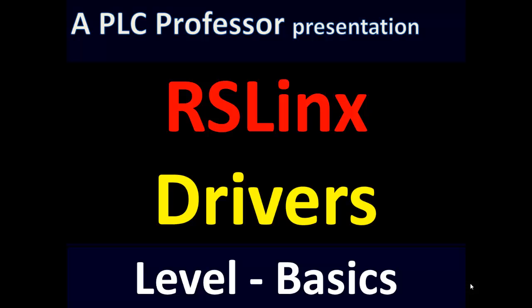The Micrologix 1100 also affords us the opportunity to configure the Ethernet devices driver and demonstrate using the DF1 driver to assist in setting up the IP address in the controller. If you are using RSLogix Emulate 500, there is a video in the Training Support playlist, TS02 RSLogix 500 Simulator, that covers all the aspects of that endeavor.